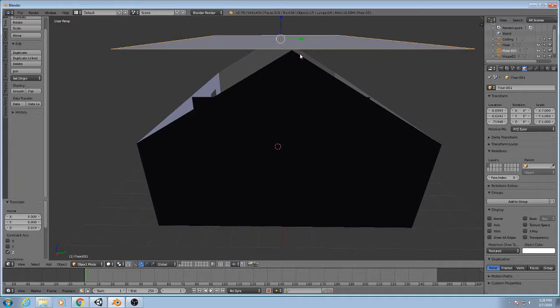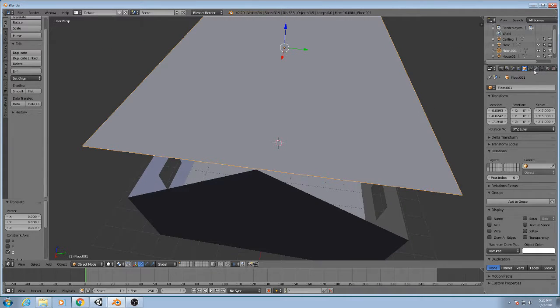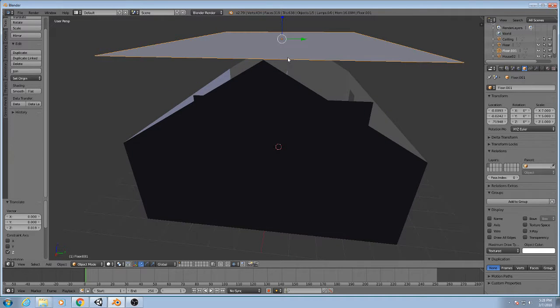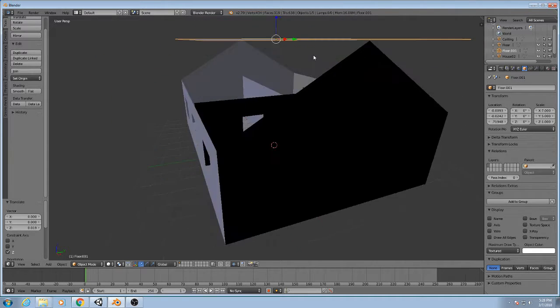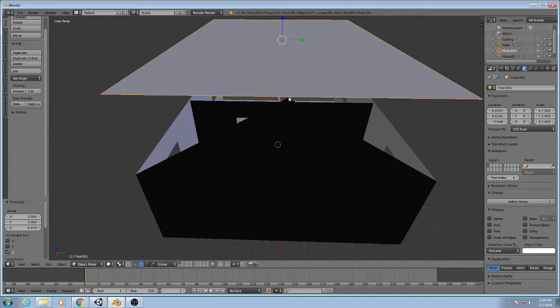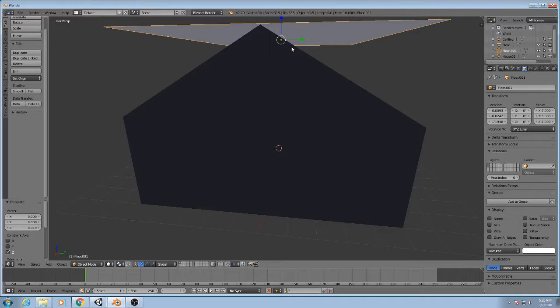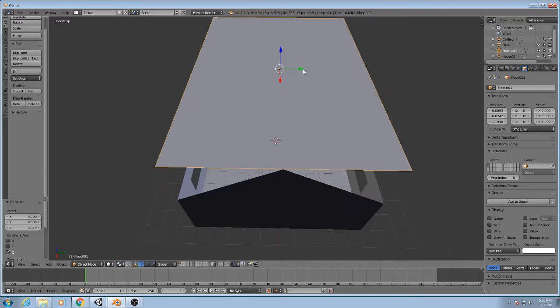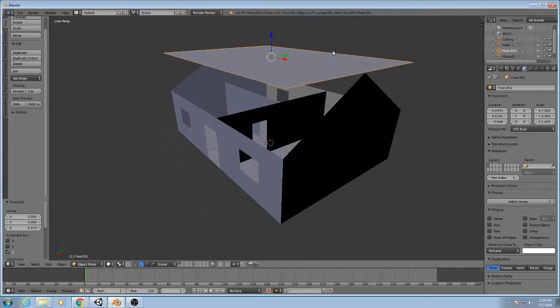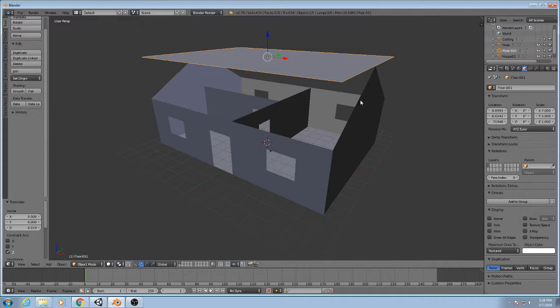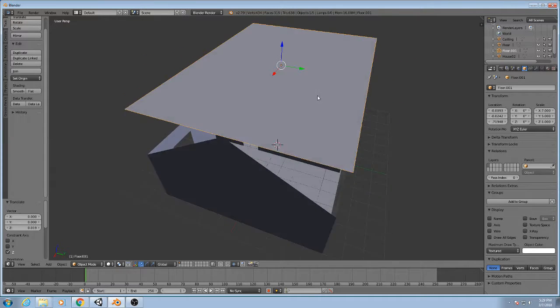Don't have to touch the roof with these at all. Yeah, you can have it about a millimeter away from each other. Again, when you do the thickening of the walls and floors and ceiling and roof, it's gonna fill up that gap that you had, so the walls and ceiling don't stick out on the finished product.